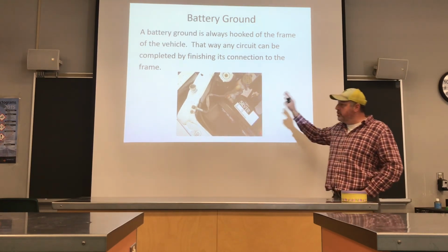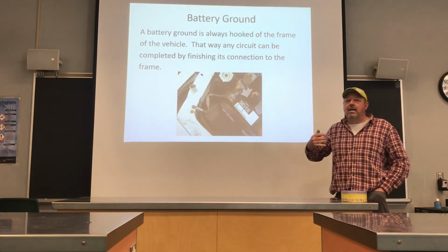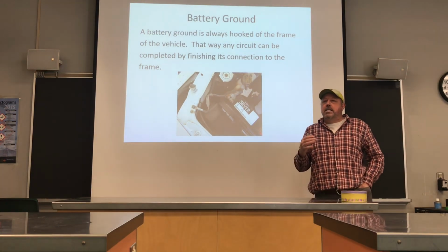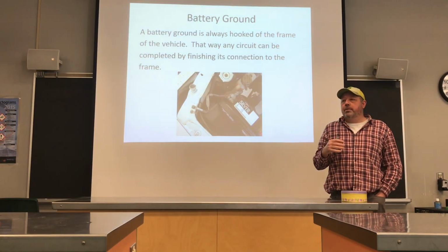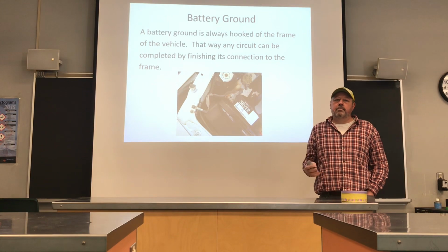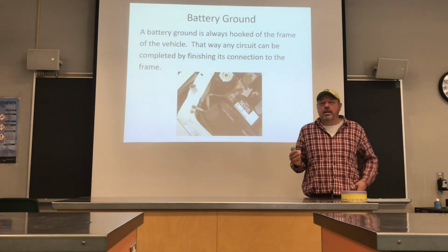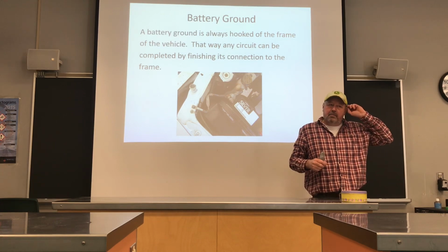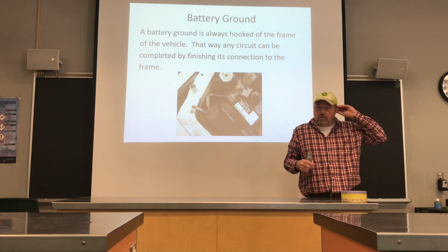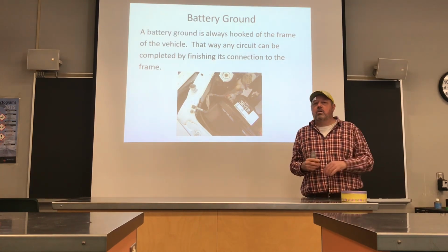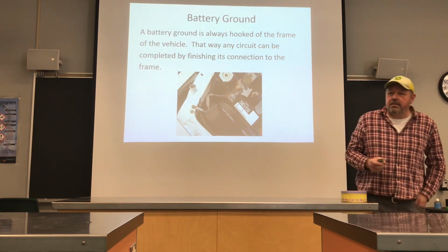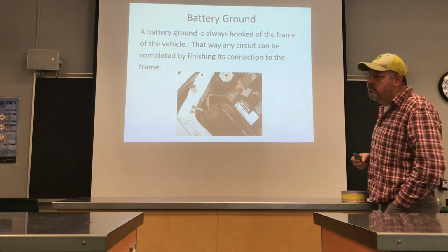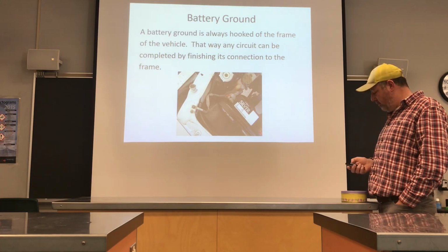That way, any of the circuits that we have in the cab or on the machine, if they need to run the ground to the frame, to save on wiring, to run it all the way back, obviously, to the battery, they can find multiple ground points on the frame to save running multiple different strands of wire for ground.